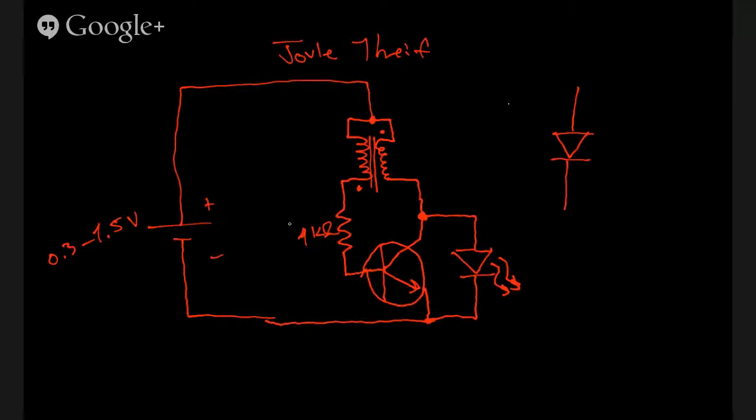So if you were to put a current through a diode and measure the voltage across it, you'd get generally 0.3 to 0.7 with typical rectifier diodes. It could be as much as 1.3. It all depends on the diode design and how much current it's meant to handle.